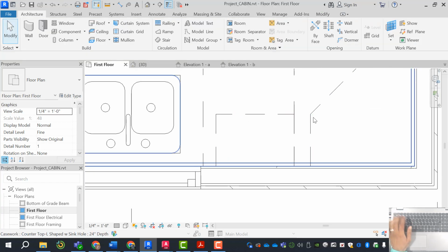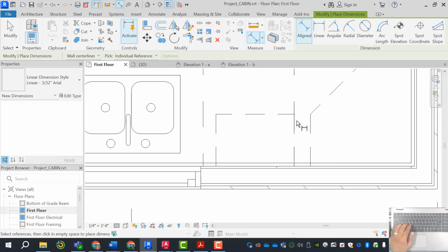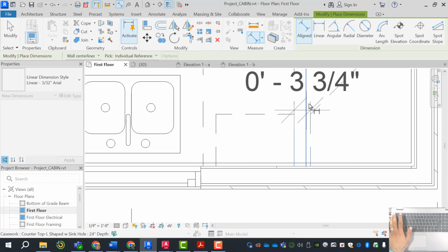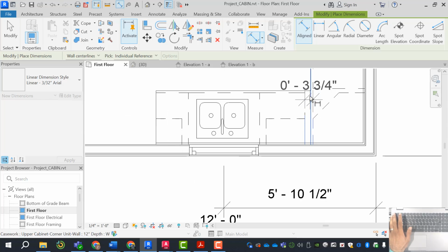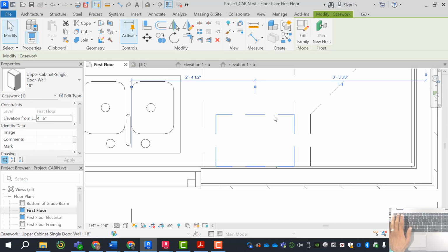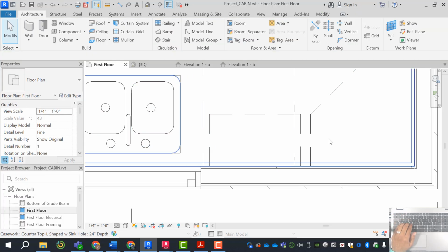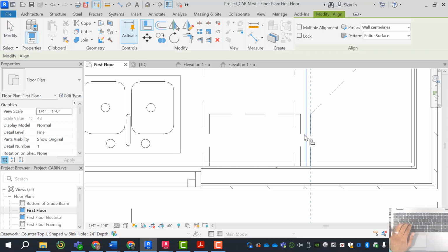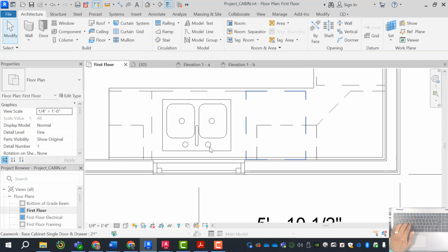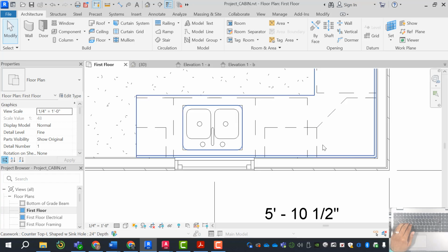And what I've just found out is that I have too much space between this cabinet and this cabinet, and there's enough space that is 3 inches and above. So I can literally upgrade this cabinet to a 21-inch, but this time align it this way, and I would still have room for the trim.